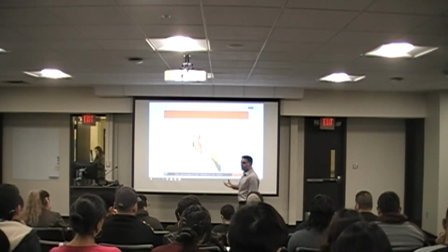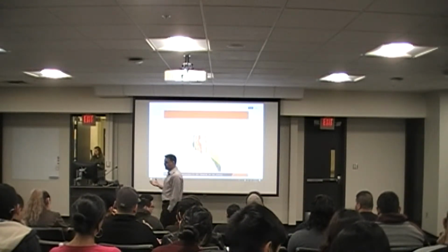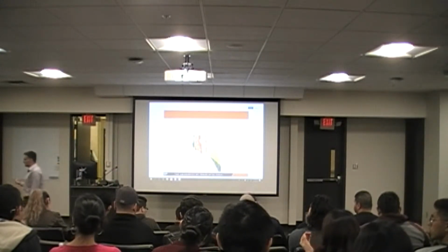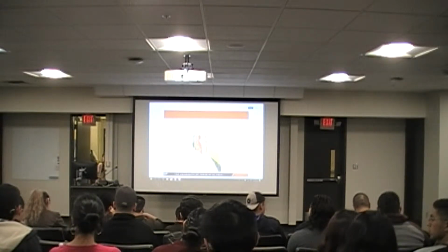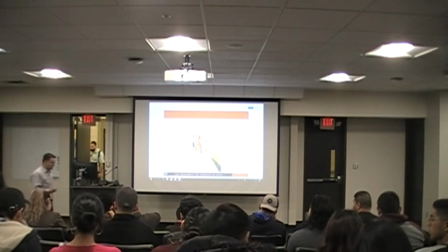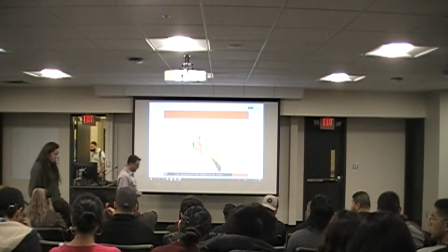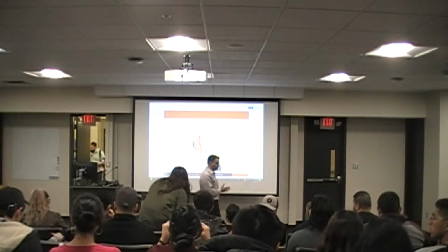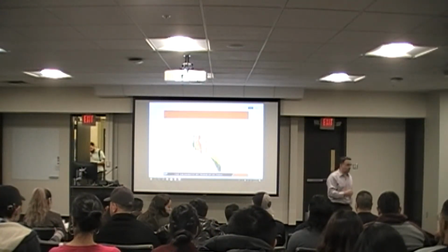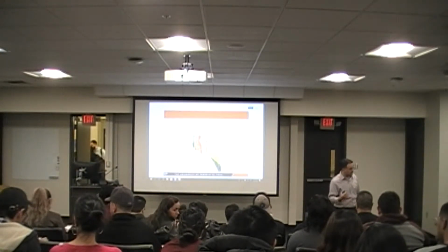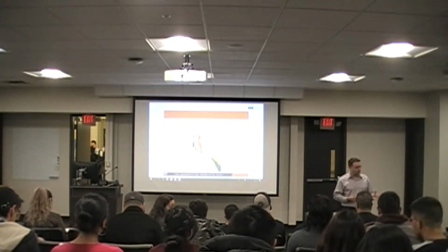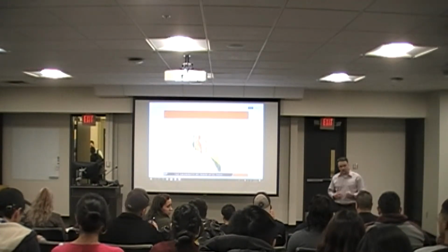On the other hand, for the case of fine-grained material, we don't look at grain size distribution. We have a way to be able to determine that. Remember we talked about the hydrometer test, right? Hydrometer test was essentially associated with the fine portion of the mix, but typically we are not interested in the hydrometer test for classification of the fine portion of the mix because the behavior of the material does not come from the particle size, it comes from the surface properties. Right? Surface properties, in a little bit more engineering or scientific way, it would be the mineralogy of the aggregates, right? Mineralogy of the particles.